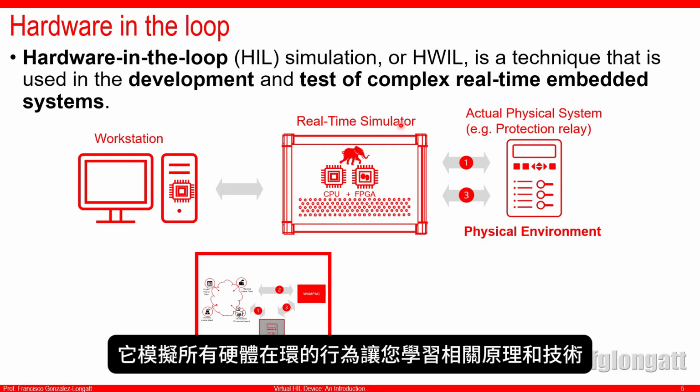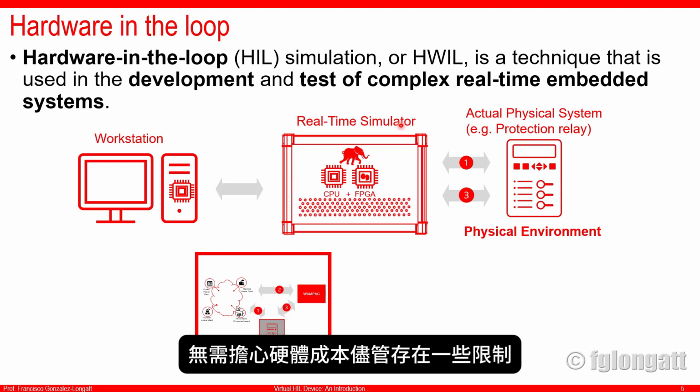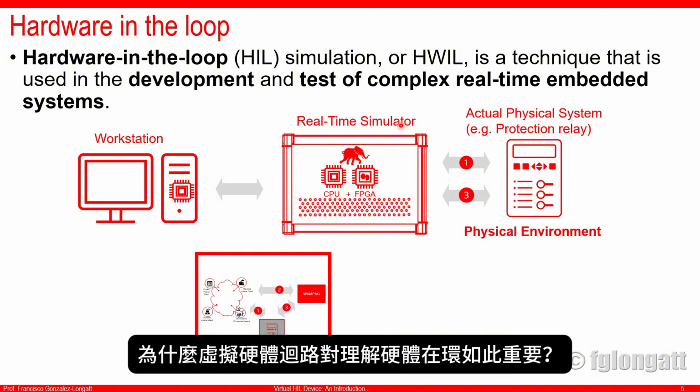The real-time simulator is typically like a classical computer, and there is a CPU inside, but also there is very dedicated hardware that allows the acceleration of this kind of time domain simulation, and that is the job of the FPGA. Of course, to control the real-time simulator, we need a workstation.